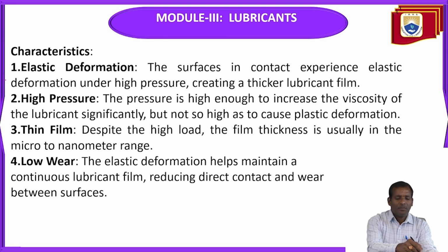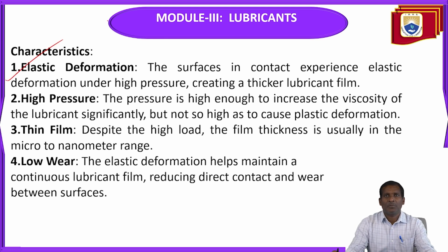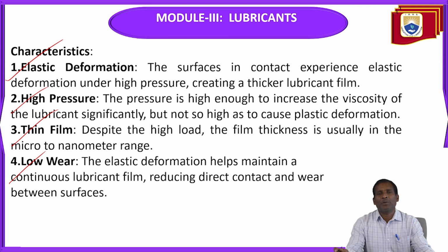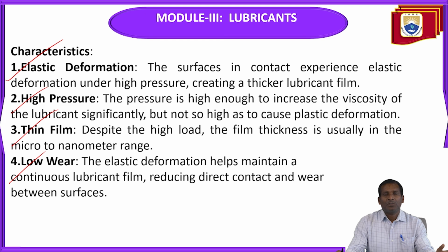Characteristics are one is elastic deformation, high pressure, thin film, and low wear. So the surfaces in contact experience elastic deformation under high pressure, creating a thicker lubricant film. The pressure is high enough to increase the viscosity of the lubricant significantly, but not so high as to cause plastic deformation.